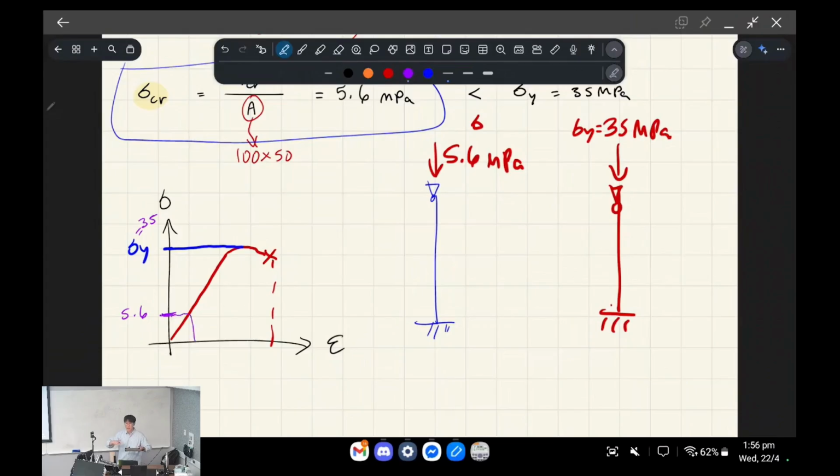So buckling is like an early type of failure mechanism that can happen in the elastic region before your yielding happens, right? And it's all to do with how long your column is and its cross-sectional properties, its stiffness, etc. Okay. So as a structural engineer, not only do you have to check how much stress before something yields, you also have to check that against the buckling stress that can cause it to fail before it reaches material yield. Okay.